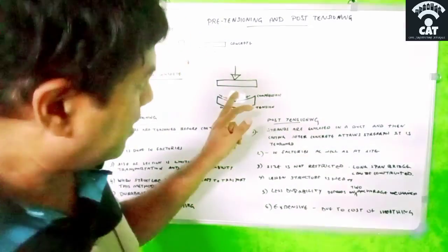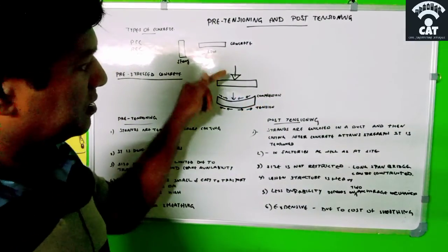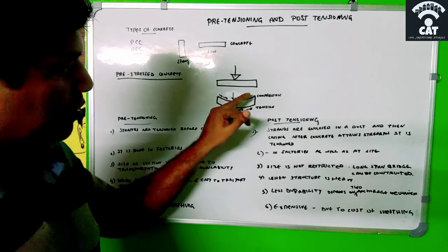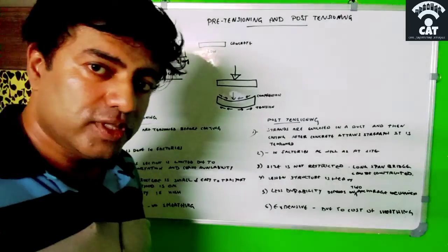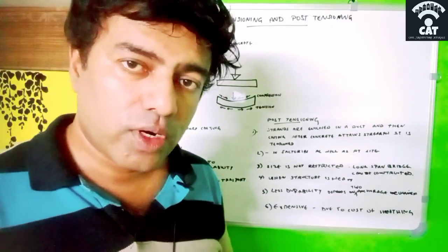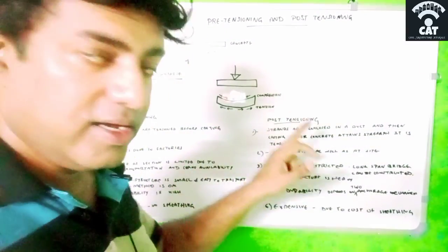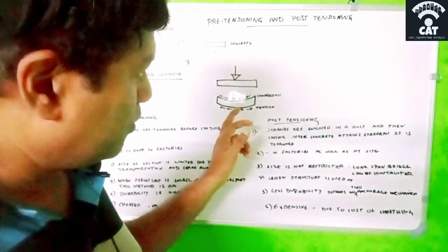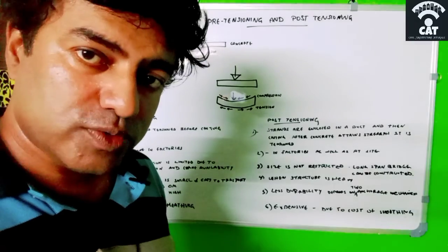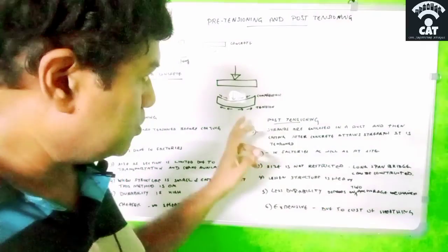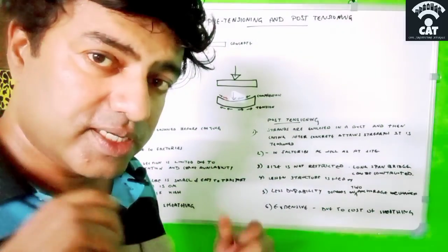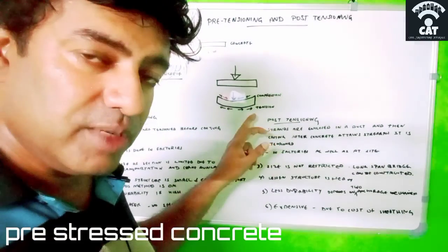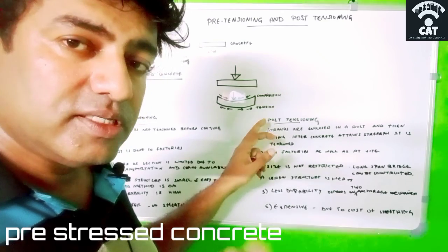That is again the same diagram we will see. They are applying the load here, and again, as I said before, compression is on top and tension is at the bottom. But now they found out that they have to add more structural members to the tension area. But the thing is that they need to reduce the size of the slab. They found that they should increase the number of structural members there, and also give tension. You have to give tension to this steel member and then place it.